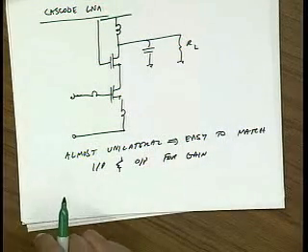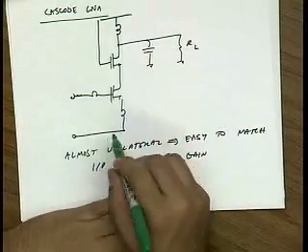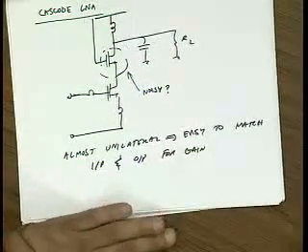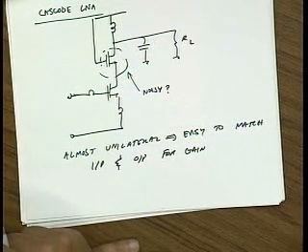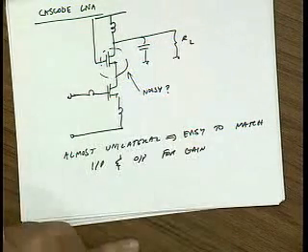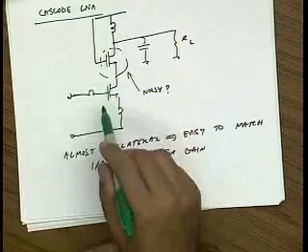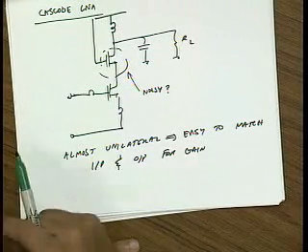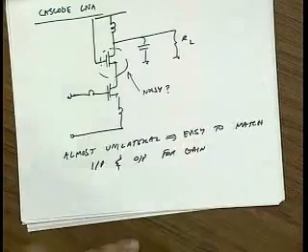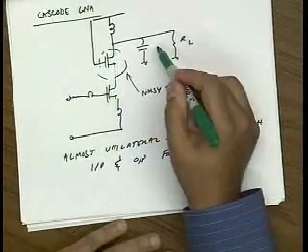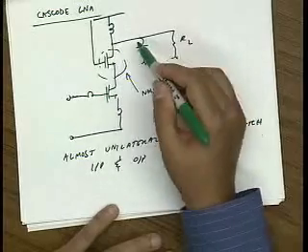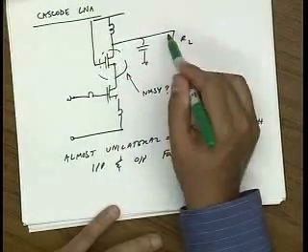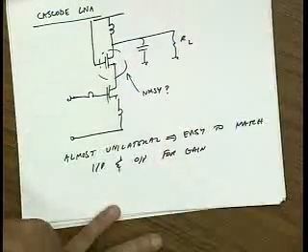Okay. So the question is, what about the noise of this Cascode device? Is this going to introduce more noise into our LNA, right? We work so hard to make this a low noise device. Now we put another transistor there, and it has the potential of messing things up. Now, if you're naive about it, you would say, well, this has some drain noise, and that's going to get dumped into the output. So effectively, it looks like I'm going to be doing really bad. I'm going to take maybe 1/4 of the noise of this device, but maybe all the noise of this device, and put that into the output. And I would get a terrible noise figure.